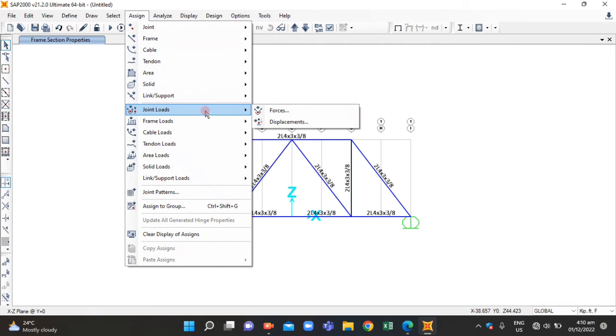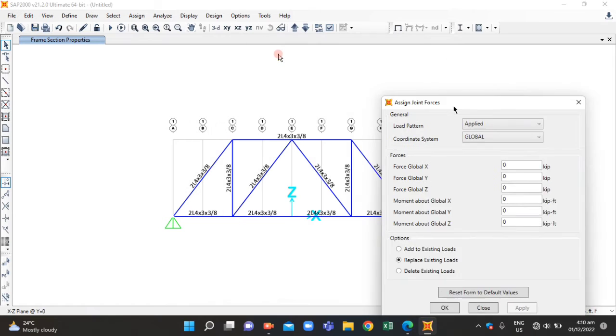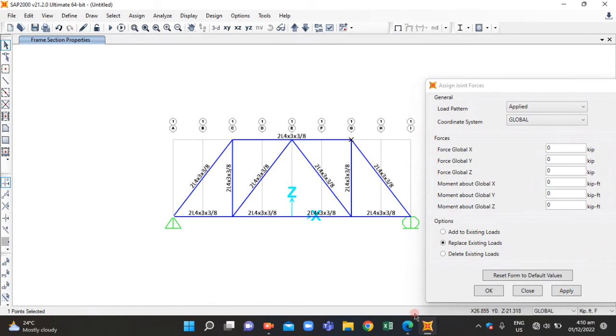Those are actually joint loads. Let me begin with this node from our reference structure at node C. It's actually here, and it's an applied load along the global x-axis, but going negative. So that's negative 2 kips. Now apply. Just have to wait, it's taking some time.